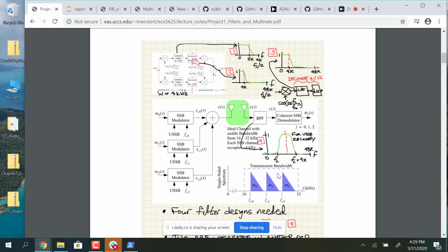If you don't design the filter properly, you hear the message M1 plus you hear M0 spectrally inverted, which sounds like gibberish. Go ahead and mess up just so you can hear it. It'll be unintelligible, but this signal will demodulate even though it's not what you want, because it's from another channel. You will hear it when you're trying to recover M1.